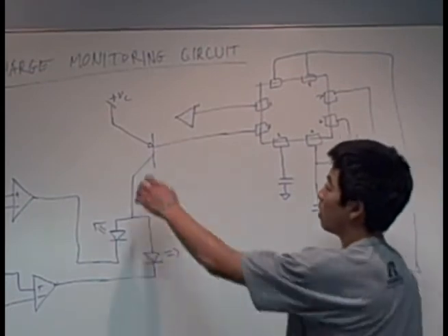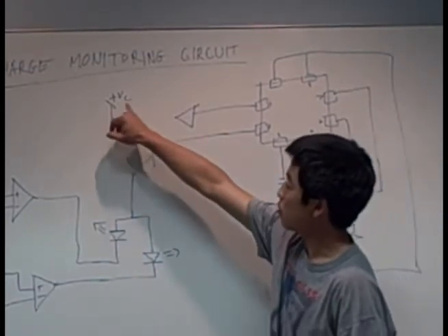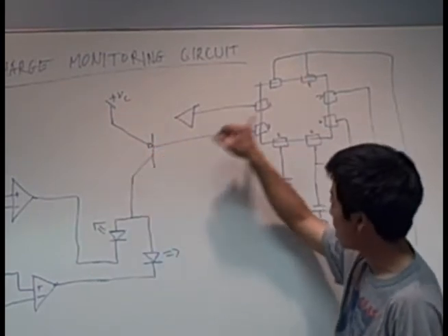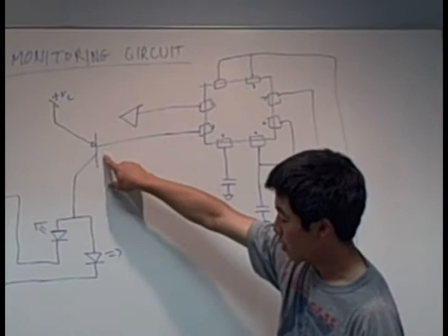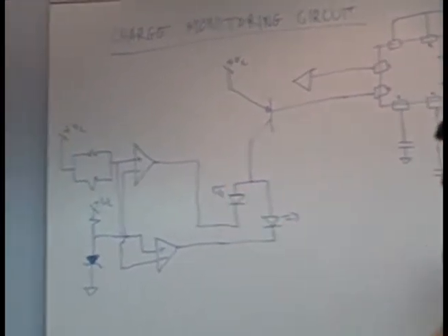And so when this voltage from the capacitor goes through here, and this transistor is on from the timer chip for 0.1 seconds, it will allow the voltage and current to flow through here to these LEDs.